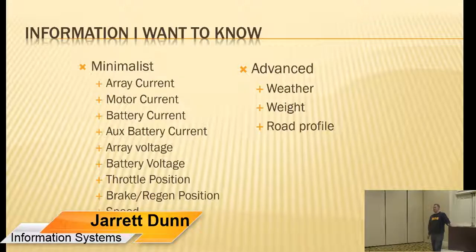Especially if you're using lead acid batteries, the voltage of your batteries is a very good indication of your battery health and how much storage you have in your batteries. If you're using lithium-ion batteries, they have a nice flat curve, but then they have a drop. If you get into that drop, you have reached the end of their charge. Knowing that you're in that drop is very important, so push it.